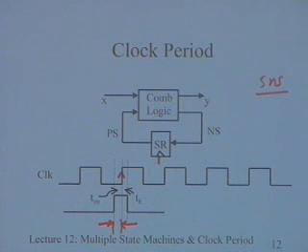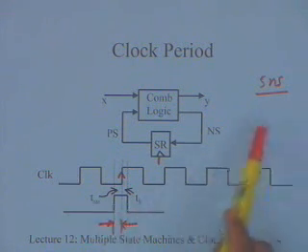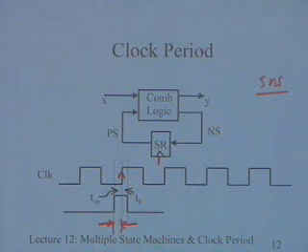If it actually changes, we will not be able to ensure that the change will be made visible in this clock or in the next clock. This is indeterminate: it may happen that the change is registered, it may happen that it is not. So it is a very error prone situation. One would like that the input does not change for the setup time before the clock.